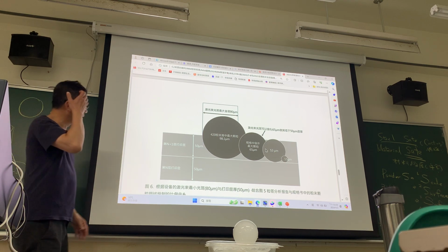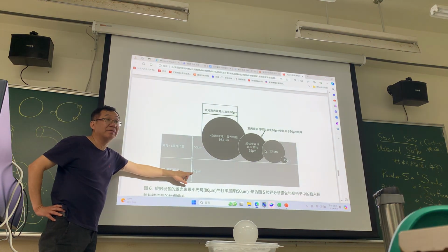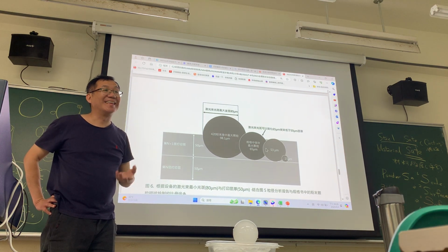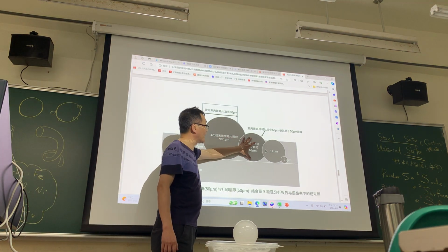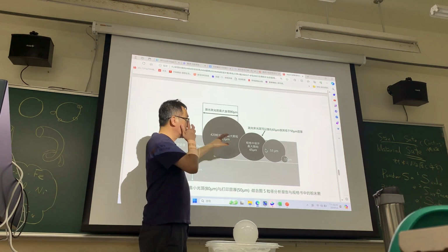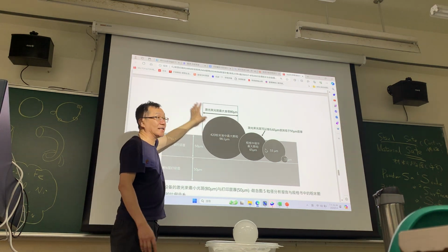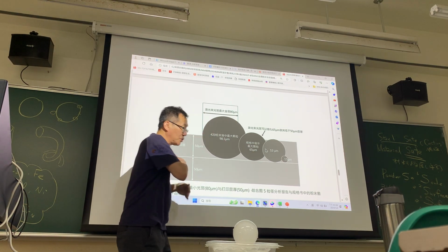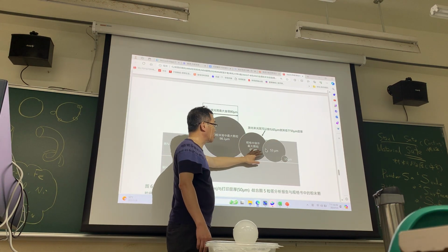So in here this is 3D printing. Okay. In 3D printing every layer is 50 micron, and your particle size should be smaller than 50 micron. Am I right? Yeah. If the particle size is too big, even if this one is melting, maybe it will be left there. In the next process, it will go outside. This particle without melting will go out, because during the rolling it will be brought up. This will become hot. So you should understand.